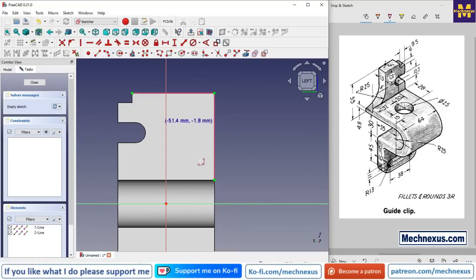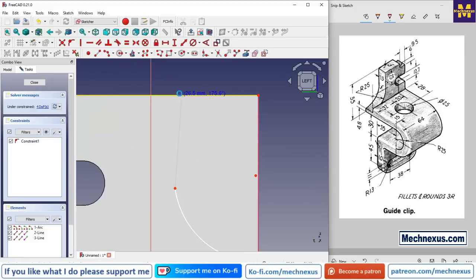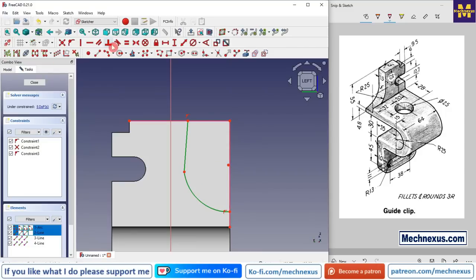Now we will select the 3-point arc and create an arc. Now select the line, now select this arc and line and add the tangency and make this vertical.